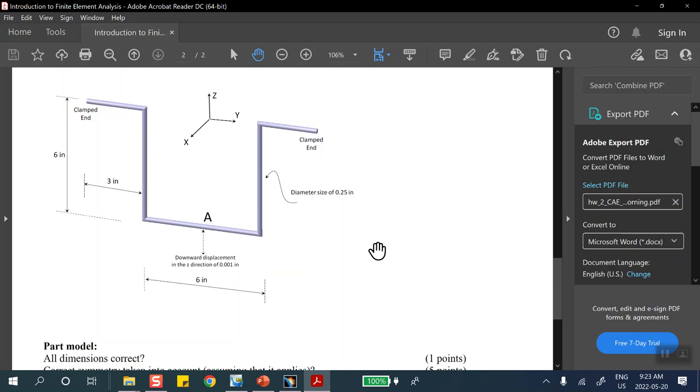So although we didn't say it, because of the way things are, if you move this thing down, it cannot go in the direction x anyway. There's no force to put it in direction x. So for your restraint, would you include that, saying don't go in that direction? No, it's not necessary. And even if you did it, you get full marks for that because you inadvertently said maybe I make no displacement in x. That is correct, but you didn't see it because it did not move in that direction. That's okay. Even if you included it, that's okay.